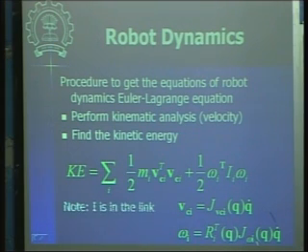Now the important thing to note is that your inertia is in the link reference frame. Typically when you have a body-attached reference frame, your inertia parameters are known better. So they are constant in the body reference frame. If you transfer them to a base reference frame, then the inertia parameters will change because it will involve the rotation matrices.